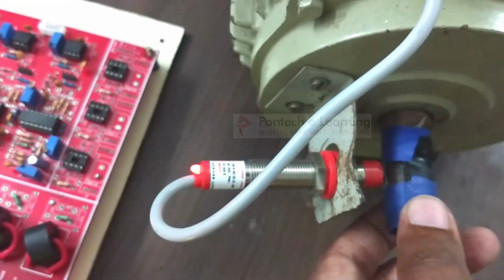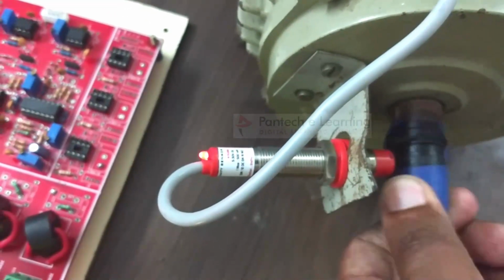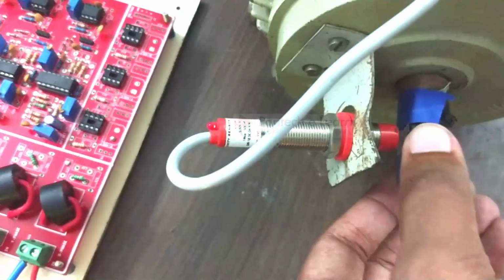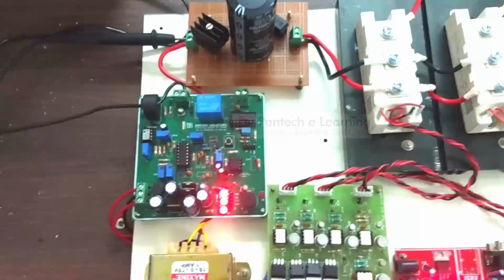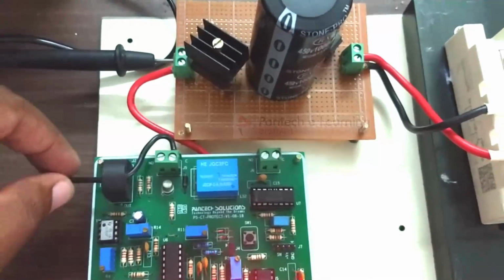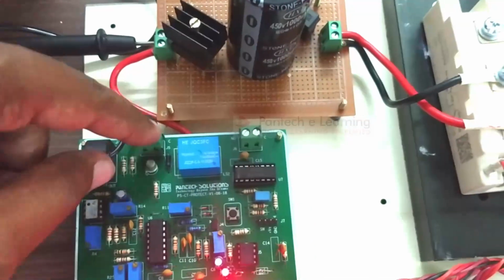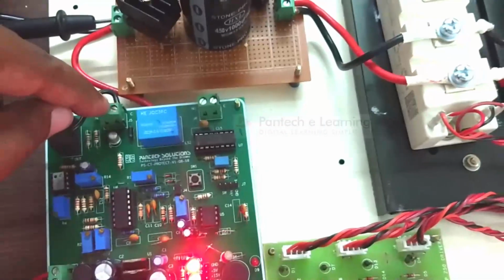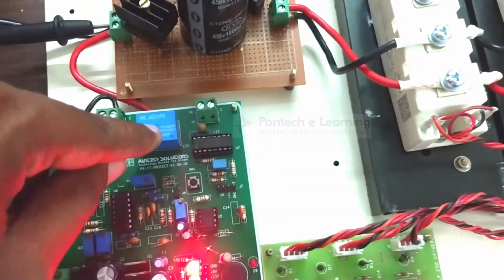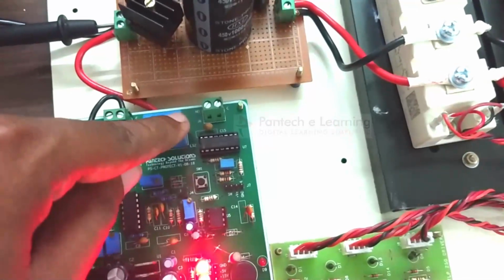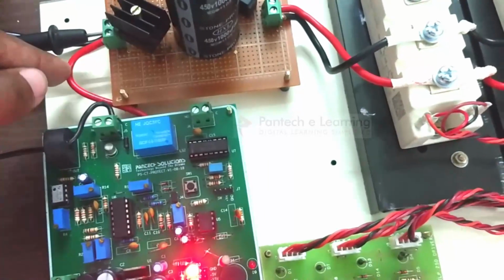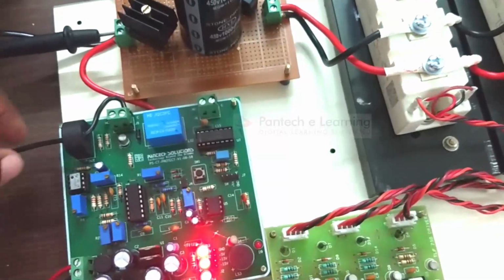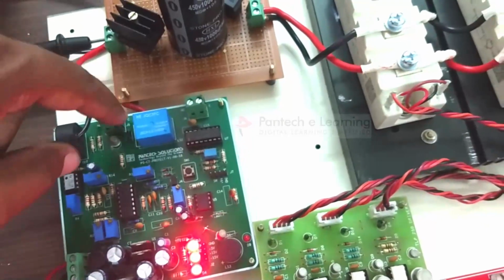You can check it over here. The proximity sensor detects whenever it detects metal, and the blinking will be there. It is detected in this region. Input AC is given to the current sensor and it is given over here. And the neutral point is directly connected over here. This point is switched by a relay. This relay is connected and the NO terminal of the relay is connected over here. You need not connect it, it is internally connected. This one you have to connect by inserting in this, and you have to connect it at this point.